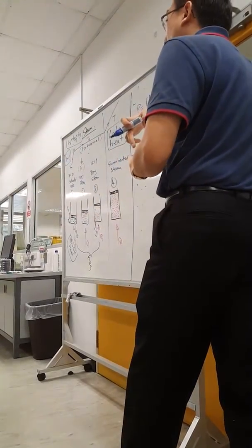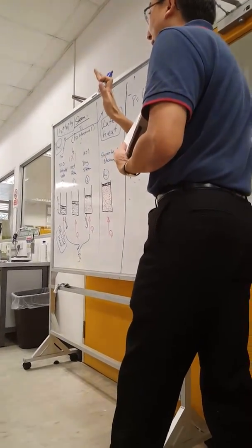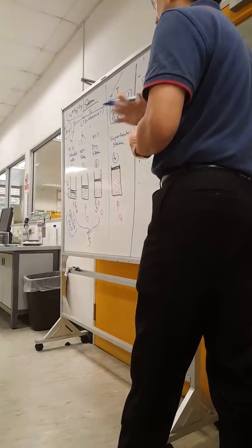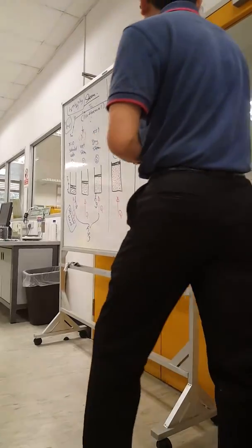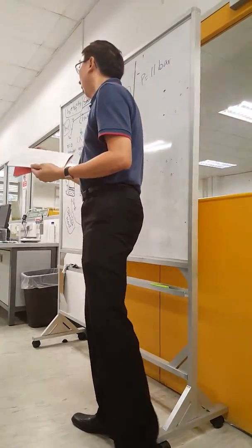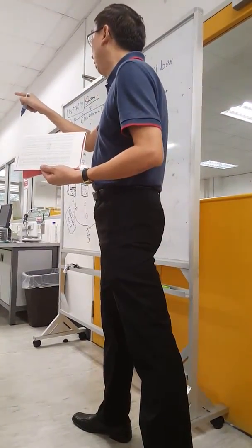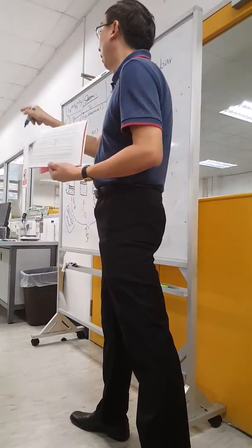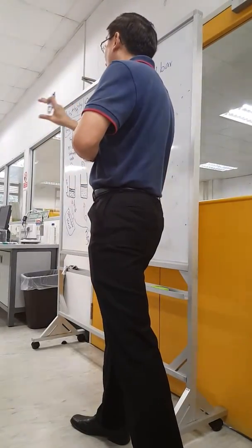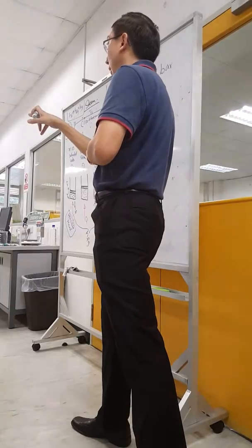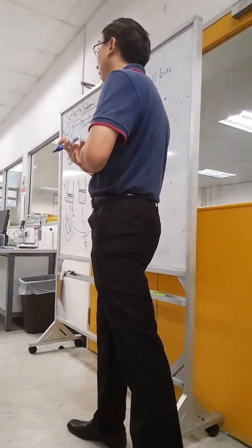Here the pressure is all absolute pressure, but you don't need to add in the 1.013, it's all added in already in the steam table. So in your lab experiment, when you want to use a steam table, you must convert to absolute pressure. Then you look onto your steam table.